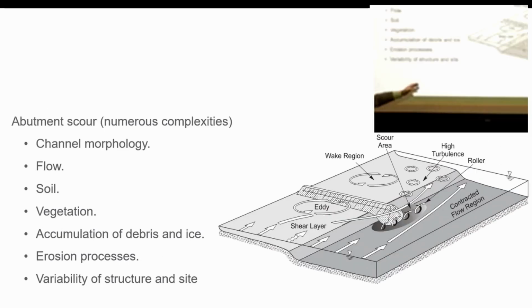In this particular example, there's an earlier example where we have an abutment encroaching into the main channel. The flow field still is quite complicated. We get a shear layer between the main channel and the floodplain. We get eddies, get turbulence, large-scale turbulent structures generated through here. We get contraction flows. And it doesn't take much scour depth to develop here before this becomes destabilized. But as I point out, how do you model earthfill structures in the lab? And this is a part, again, where we're at the frontier of ignorance.